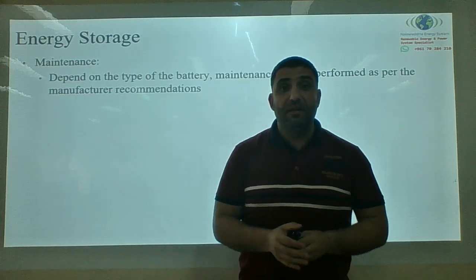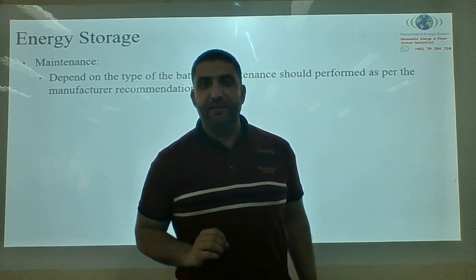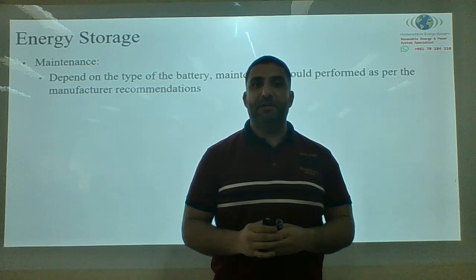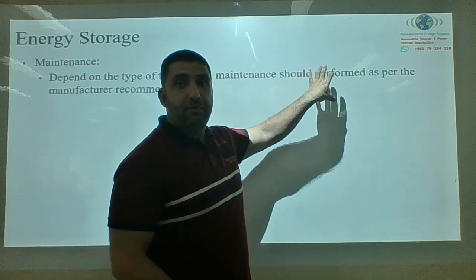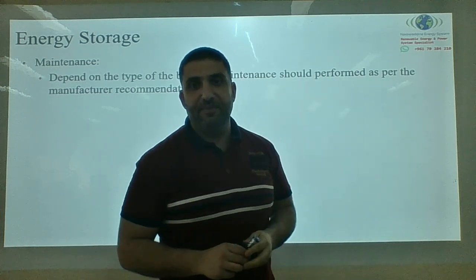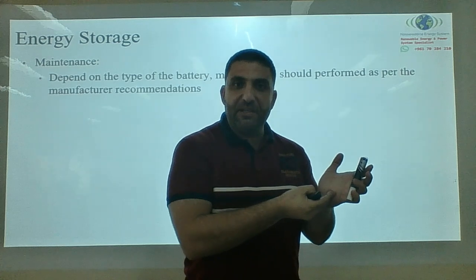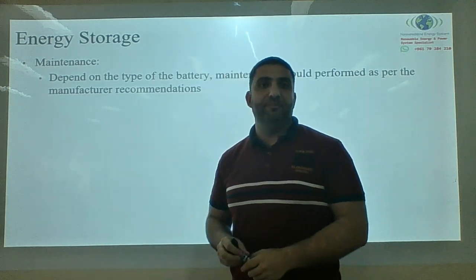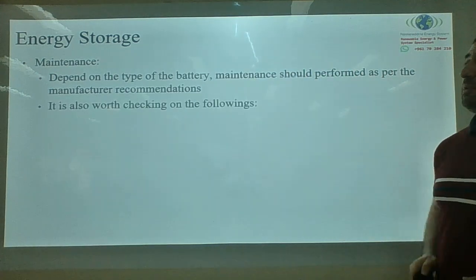Please, whenever you do a job for your client, you install an electric system, photovoltaic, inverter, and a battery, get a plastic sleeve, put it somewhere, and put the data sheet inside. So when someone comes back, they can check what's been done, when was the last time, and all this information will be available to them. Please do this to help with the maintenance.